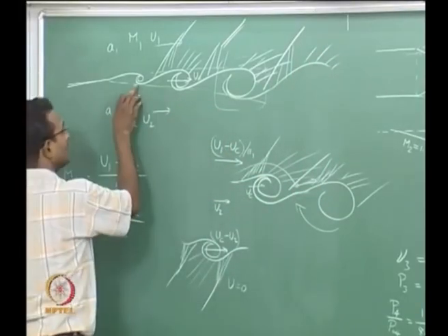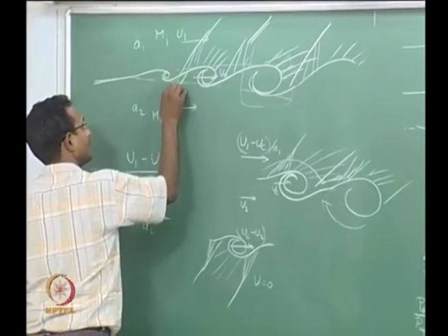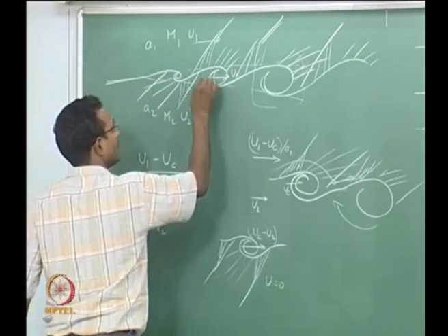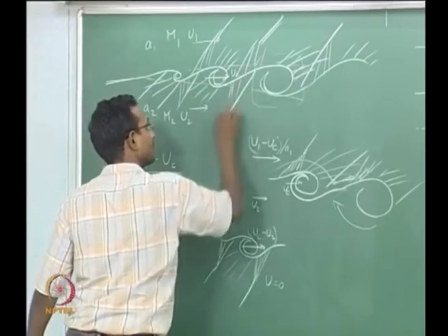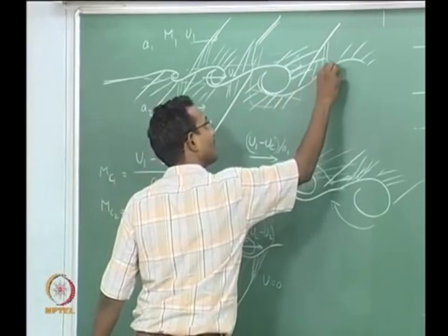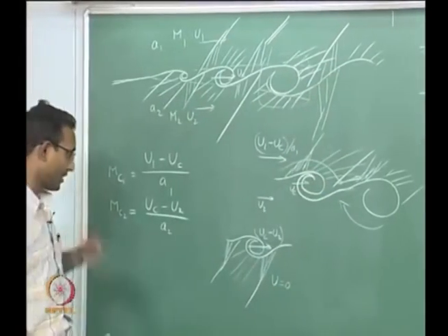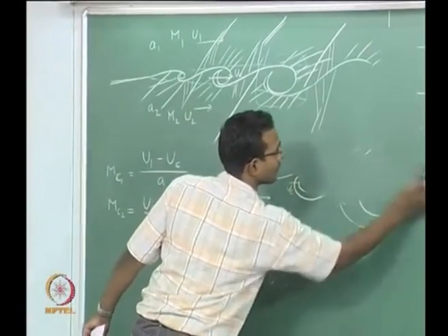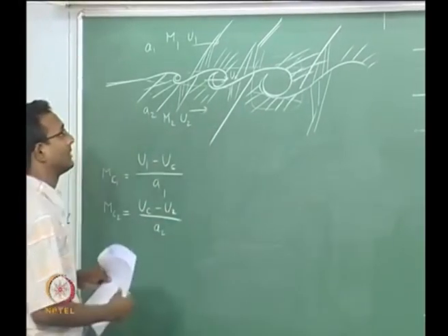On the bottom, this fluid is going faster than the outside, so there will be a shock, a set of compression waves, and then a whole bunch of expansion waves, and then another shock, and the structure repeats like this. Shock, set of compression waves, and this structure repeats. I will remove this thing which is confusing, and I will have this whole thing happening there.